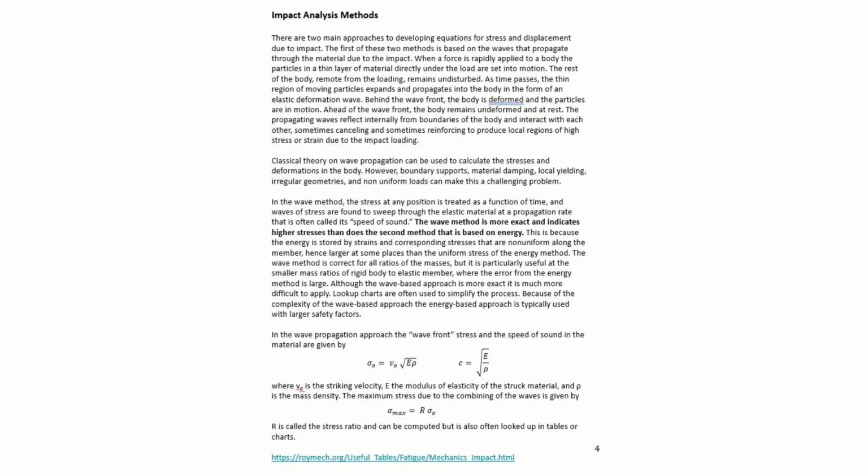In impact analysis, there are generally 2 basic approaches to solving the problems. The first one is the wave approach. When an impact hits a material and a force is rapidly applied to a body, the thin layer of material directly underneath the load starts to move, and a wave propagates throughout the undisturbed material.